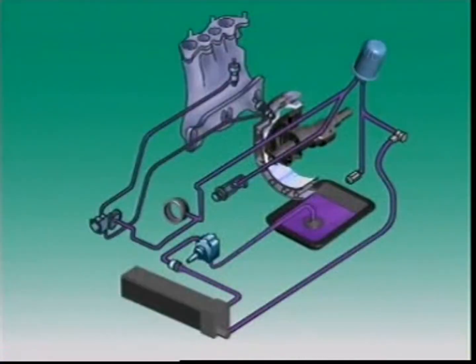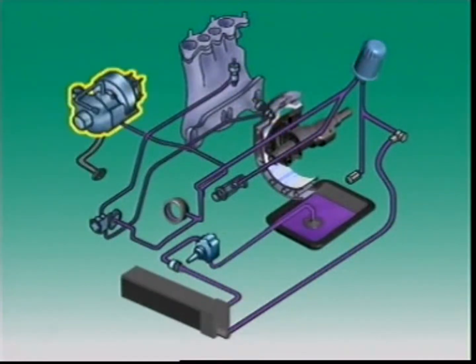The rotary engine uses oil injection. A pump sends oil to oil nozzles in the intake manifold and to oil nozzles in the intake passages in the rotor housings. Oil from these nozzles goes to the engine and lubricates the rotor seals. If the engine has a turbocharger, oil lubricates it as well.